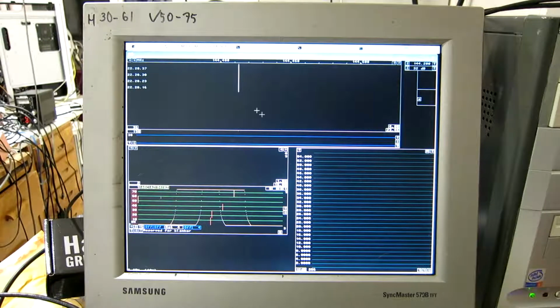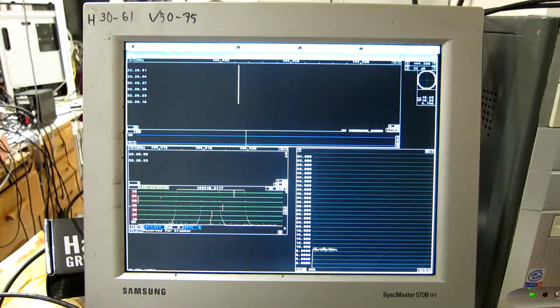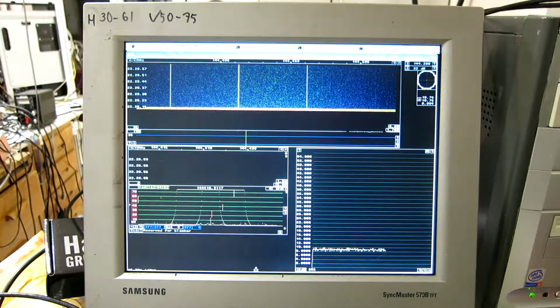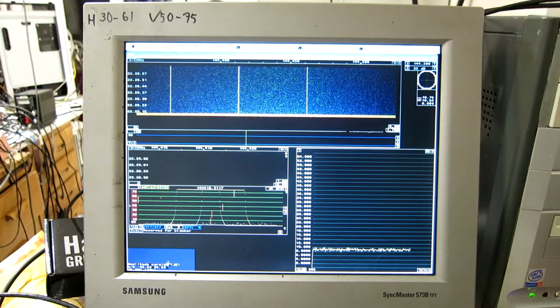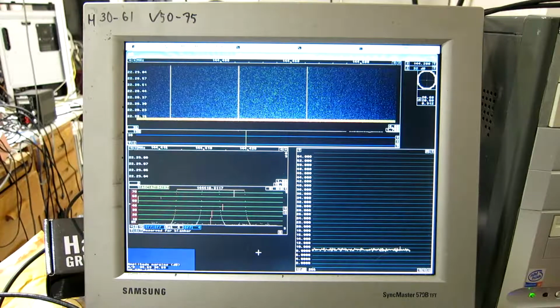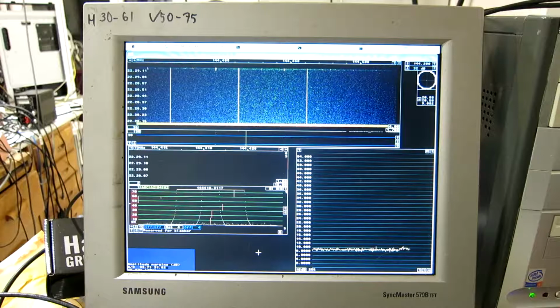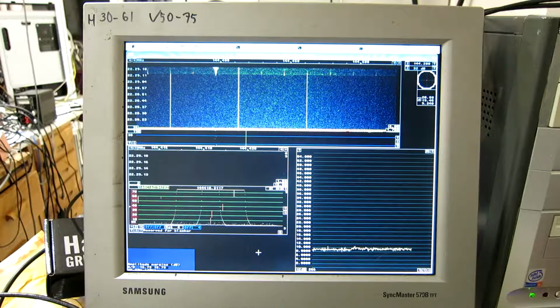I can now look at the dynamic range. That is, how strong can a signal be above the noise floor before saturation happens. So I look at the noise floor, I right click in this box, so here we have the noise floor, and press A, and then bring up the variable signal generator, the frequency variable thing, and you can see the noise floor goes up, and we have artifacts.